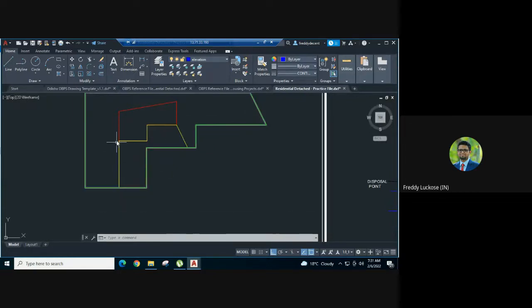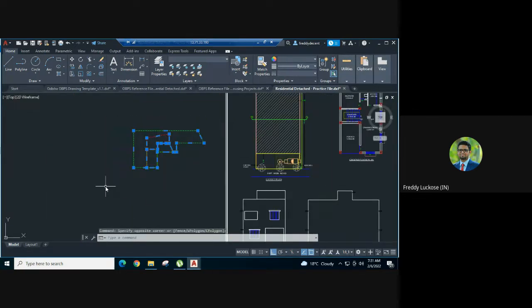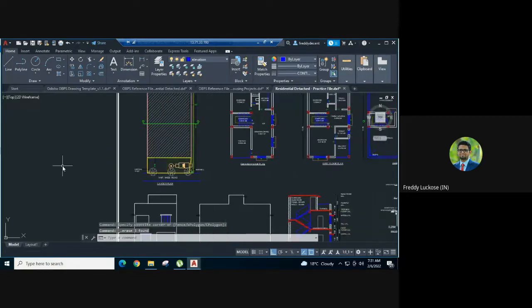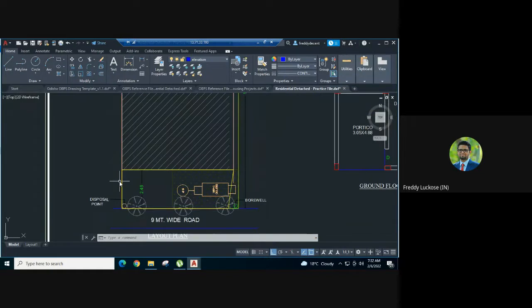Now the system will automatically calculate all the distances, infinite distances that come up in the geometry from building footprint to the plot. And it will give the minimum setback at this value, the shortest one. So using this methodology, you can create any kind of shape you have as per the project design. And another important point that I have to make here is there shouldn't be any multiple polygons here. So if there is only one building block in your project, there shouldn't be two polygons with the same layer name called building setback for front setback. There shouldn't be two polygons.